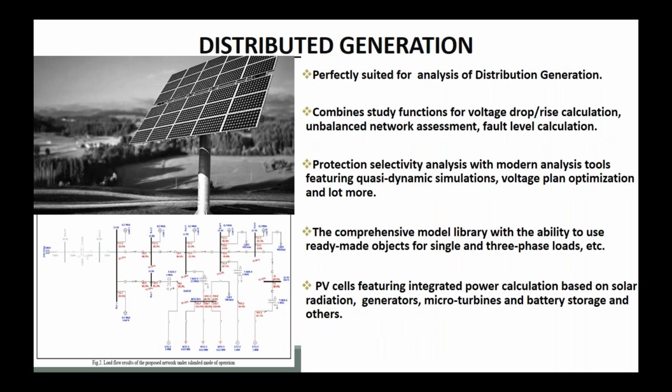Distributed generation. Generation at the distribution level comes with new challenges for the distribution planning engineer due to reverse power flows, voltage drops, and extreme variation in equipment loading. DIgSILENT offers various generation technologies such as synchronous and asynchronous generation units, PV cells, wind turbines, fuel cells, and micro turbines. Typical studies include steady state and dynamic analysis. PowerFactory is the ideal tool for analyzing the impact of distributed generation on the network.